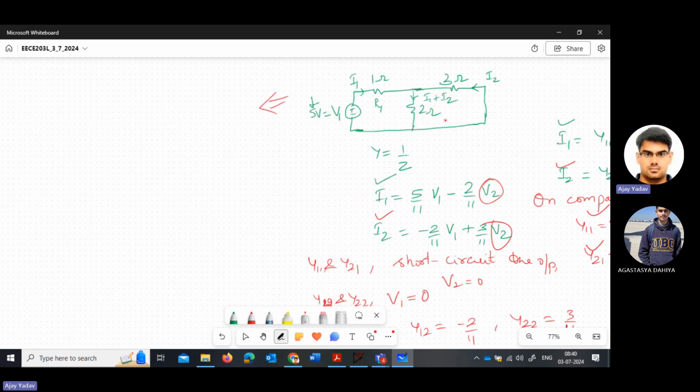If you want to calculate, first of all, we will do this theoretically. So this is the current which is coming here. This is the voltage. These two are in parallel, right? So the equivalent of this value is how much? This is 1 ohm, and these two are in parallel. So 2 into 3 divided by 3 plus 2, that is 6 by 5.